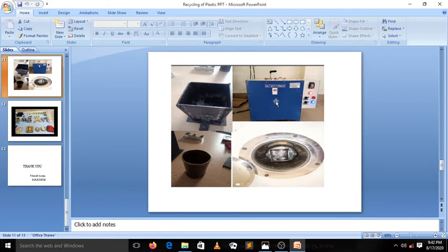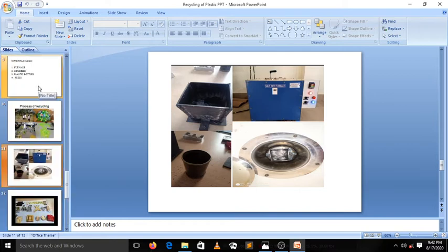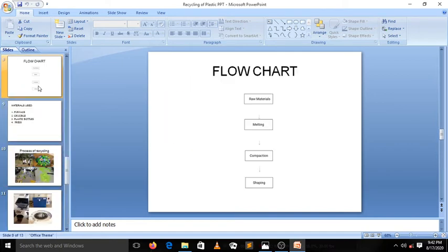It is a furnace. This is the inner side of the furnace, and we keep the chipped pieces into this barrel, and this barrel is kept into the furnace. We apply heat to that barrel. It is about 250 degrees centigrade, the melting point of PET. We should not go to the melting temperature, we should go to the softening temperature, which is about 180 degrees centigrade.